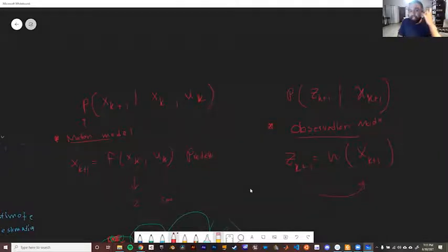So these equations exist, but the actual quantities that we are going to estimate are probability quantities. And since the Kalman filter assumes that everything is Gaussian, that was assumption number one, Gaussian or normal, what are the quantities that we have to estimate in a Gaussian distribution? It is simply its mean and its covariance. As long as we can estimate its mean and covariance, we are pretty much estimating the entire probability of the system. The mean will give us the best, most average estimate that we can assume, so the final answer should be the mean. And the variance will tell you how sure of your answer you are. Again, I will do a simple example now, and this will be a bit clearer.